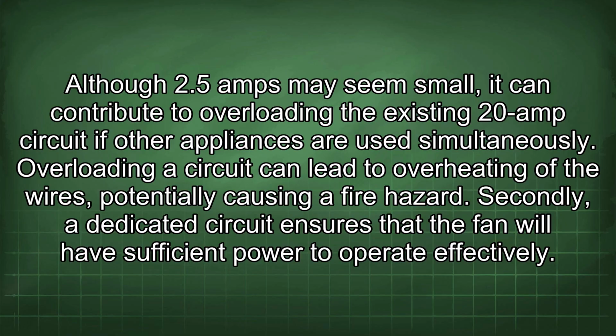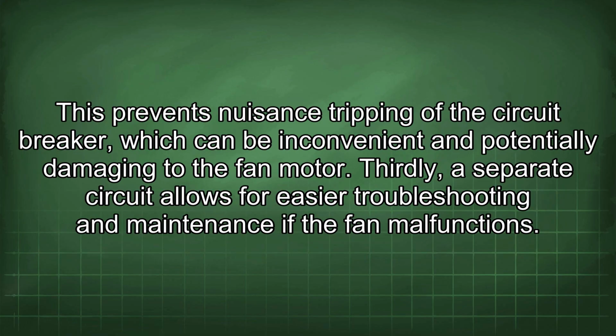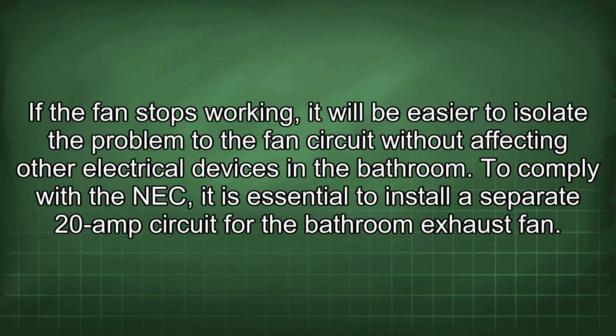Secondly, a dedicated circuit ensures that the fan will have sufficient power to operate effectively. This prevents nuisance tripping of the circuit breaker, which can be inconvenient and potentially damaging to the fan motor. Thirdly, a separate circuit allows for easier troubleshooting and maintenance if the fan malfunctions. If the fan stops working, it will be easier to isolate the problem to the fan circuit without affecting other electrical devices in the bathroom.